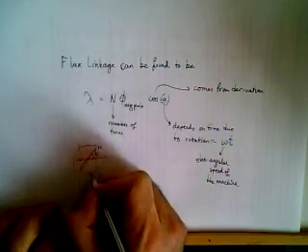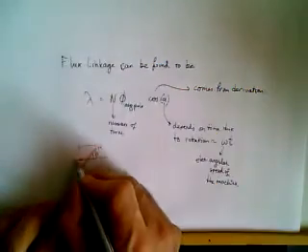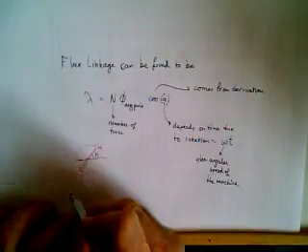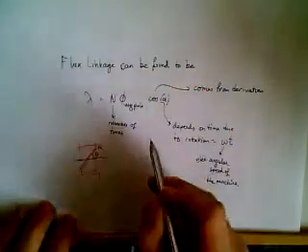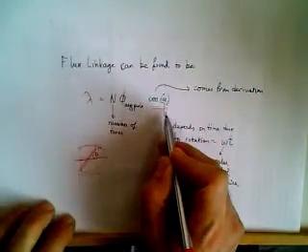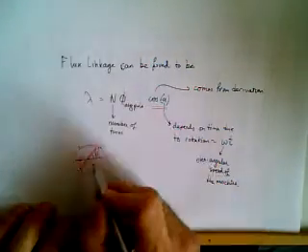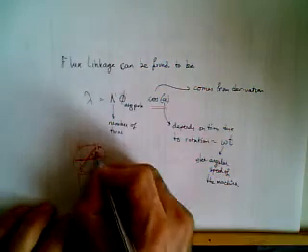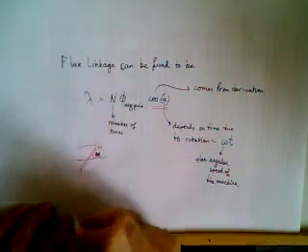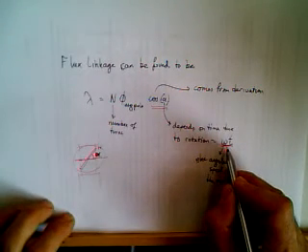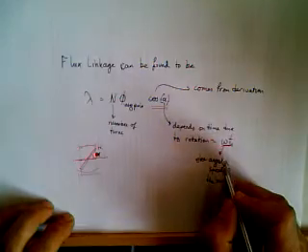When theta is 90, it does not link at all. When theta is 0, it is maximally linked to the stator flux. So we have a time dependence of the flux linkage with respect to angle alpha, and this should be replaced by alpha here. Alpha depends on the radial angular speed and time.